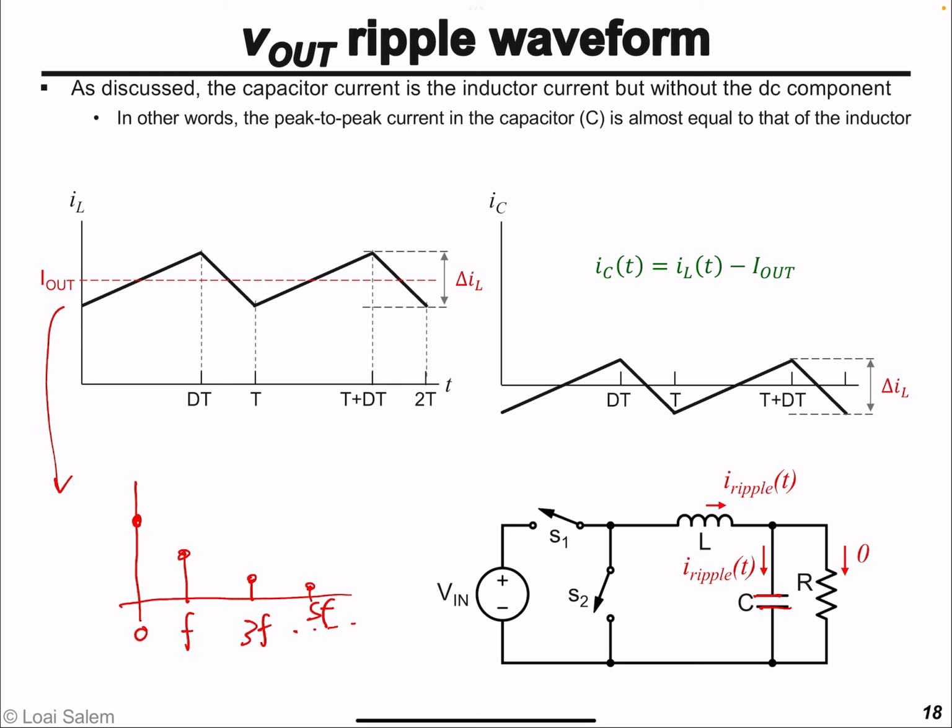We mentioned that since the LC filter or RLC filter is basically a linear network, we can apply KCL at each harmonic component. At DC, the capacitor is open circuit, so basically all of the DC component will flow into the load resistor.